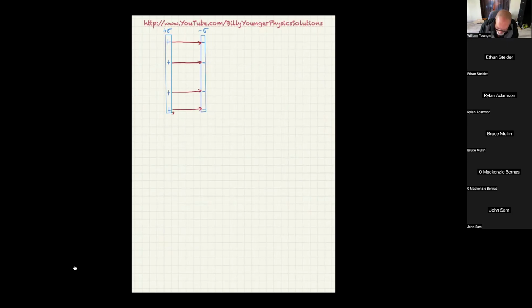So that's why I drew that little box there. And then it's going to bulge out and then start to bulge back in and come back to the conductor perpendicular again. So that's how the electric field is going to behave at the edge of the parallel plates. Same thing here. It's going to go up, reach some maximum distance out, come down, go like this. And again, this is perpendicular and this is perpendicular. Okay, but that's basically how the electric field is going to be.